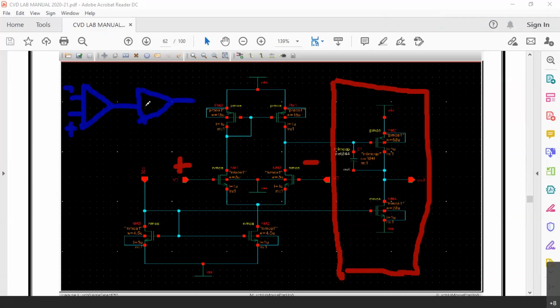As I've been telling you earlier, in your next semester, you can take the op-amp design itself as a mini project for those of you who are interested in VLSI design. You can try to design your own operational amplifier, maybe 2-stage, maybe 3-stage also. You can have an intermediate stage in between, then you can have a high gain stage. At the output, you can have a power amplifier also. You can refer to the published articles or even to the textbooks, and you can design your own operational amplifier, and you can measure its gain and bandwidth, and you can proceed with the physical design or the layout design also. That will be quite interesting.